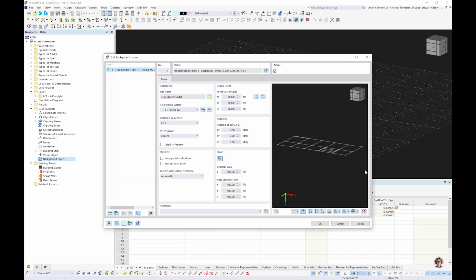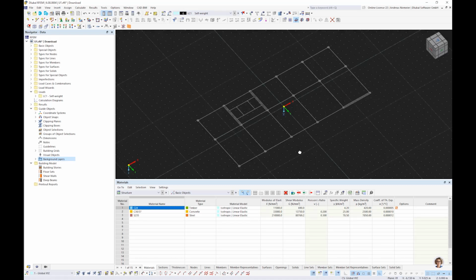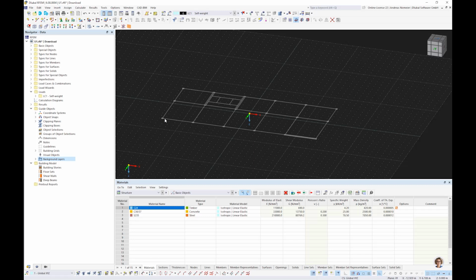This layer gives me the coordinates and the sizes of the buildings mainly. And because I see the DXF is rotated, I can change it here. You define the angle and the program rotates it. After confirmation, we have it now in our plane, similar to the grid points, and can start modeling.